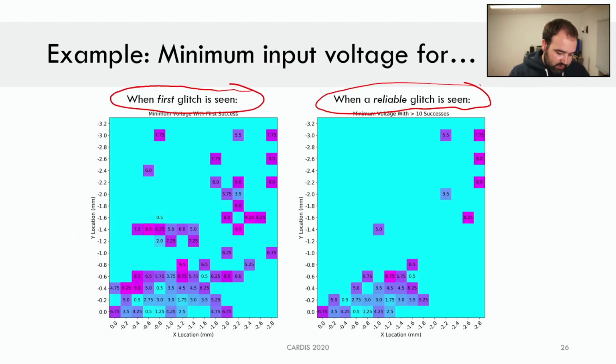You can see, for example, up in the corner, it's actually interesting. You see these 3 locations where you do get glitches with nothing in between them. So we can see there is quite a bit of spatial sensitivity here. And these are reliable glitches we're getting, so it's not just that we happen to get a fluke of some glitches at one location and none at the next. We also see some nice sensitivity down here.